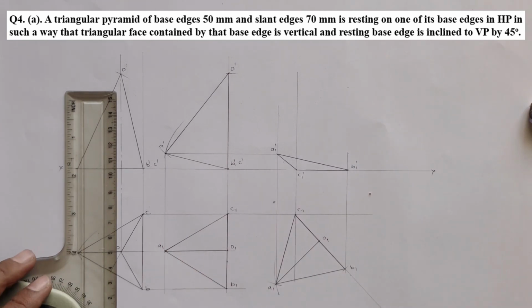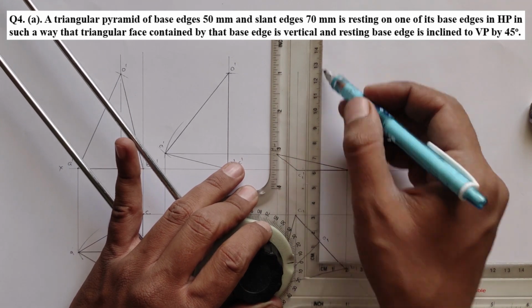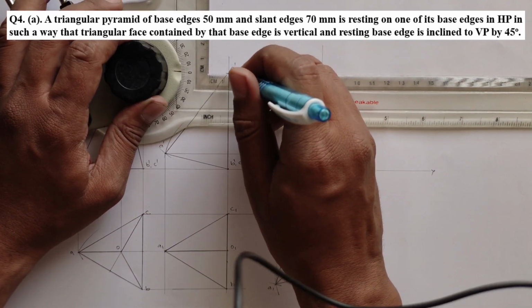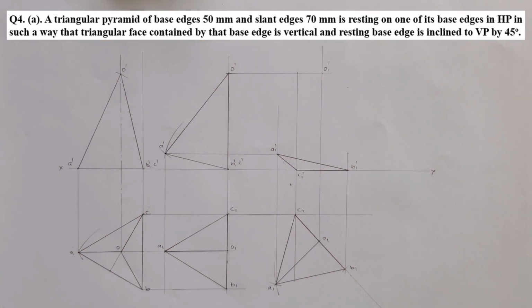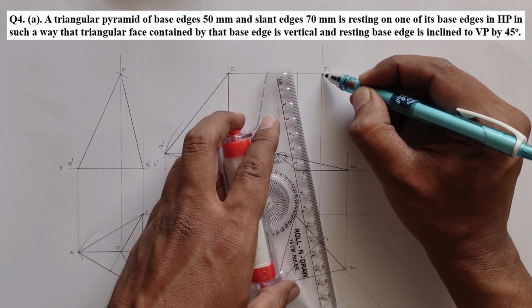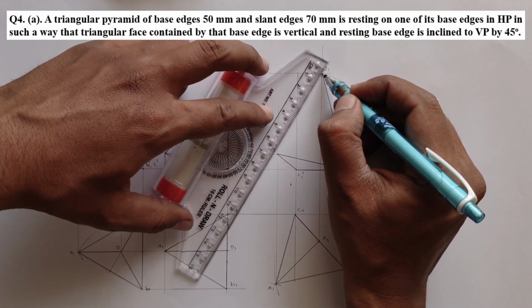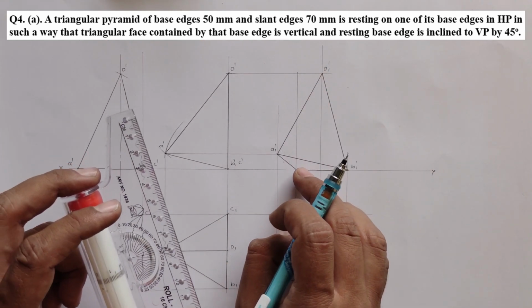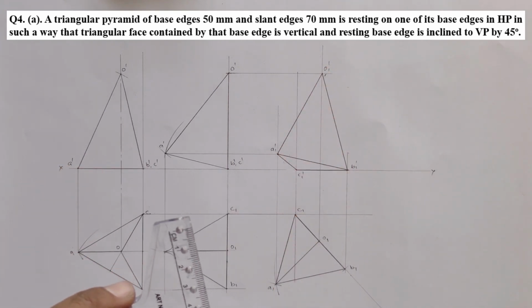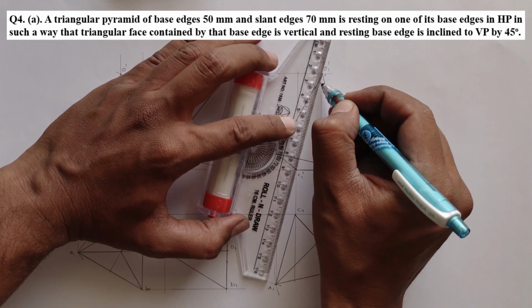Now the apex. O is on this point here, and on this horizontal projector. So this becomes O1 dash. Now the outermost slant edges, that is BO and AO, will be visible, whereas CO is passing through this image, as this is a solid, so you cannot see this edge, so it should be drawn as a dash line.